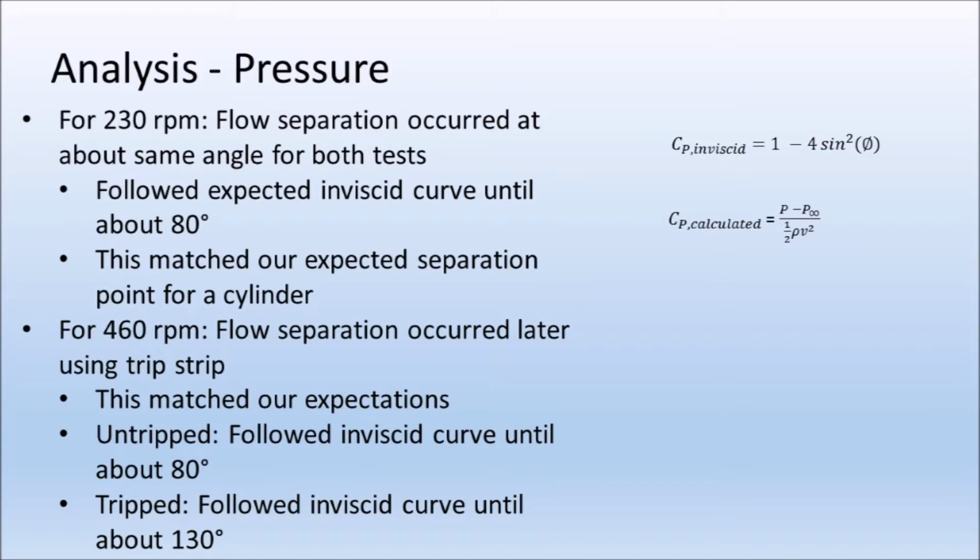I believe this may just be due to the nature of the pressure probes not being perfect measuring tools and us not having time to perform multiple runs of data collection. The reason it reached its highest point toward the trailing edge of the cylinder is because with laminar flow, it took until that point for the boundary layer to reach a state of turbulence.